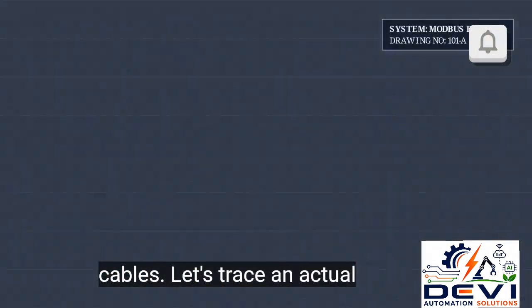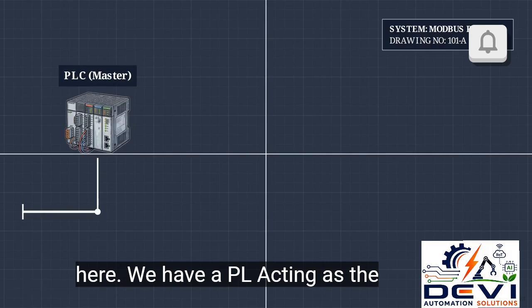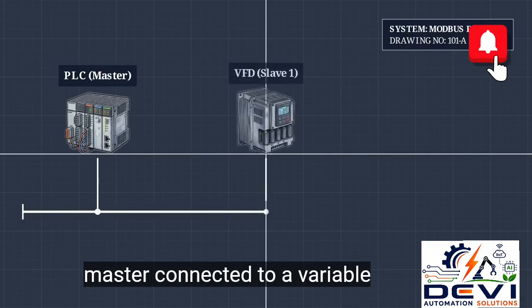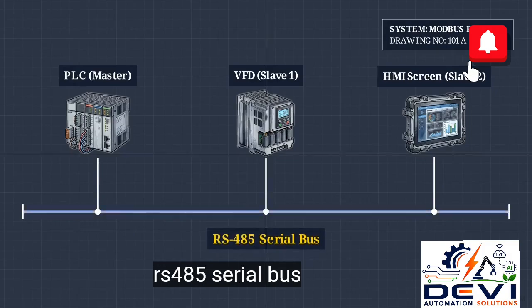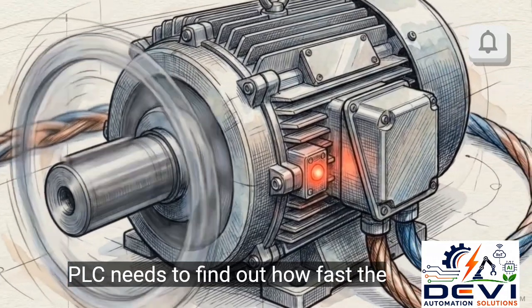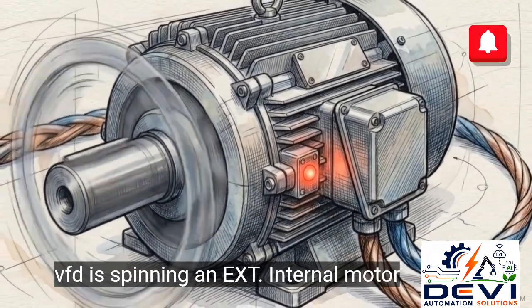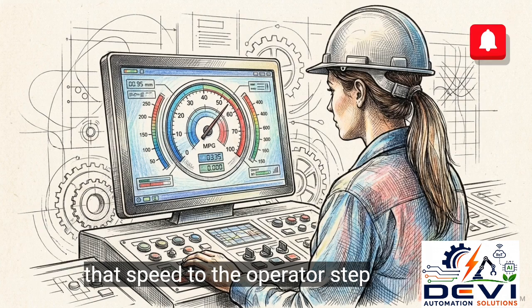Let's trace an actual sequence through this electrical schematic. Here, we have a PLC acting as the master, connected to a variable frequency drive and a touchscreen HMI on a single RS-485 serial bus. The objective is straightforward. The PLC needs to find out how fast the VFD is spinning an external motor, and then update the HMI screen to display that speed to the operator.